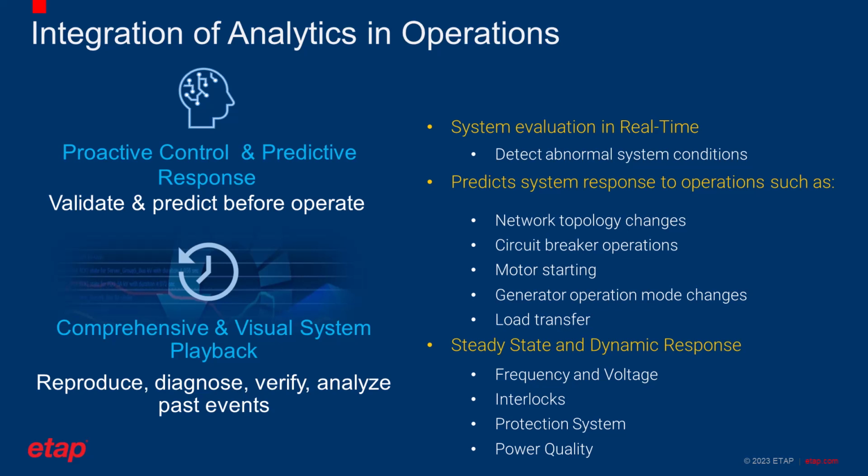The SCADA solution also provides the tools to predict electrical system response before an operation is executed, when the operator needs to perform network topology changes, circuit breaker operations, motor starts, generator operations, and more, including load transfers. They can simulate and validate the response of the electrical network to avoid unforeseen conditions such as overvoltage, undervoltage, underfrequency, protection system operations, power quality issues such as resonant conditions. The predictive simulation allows you to see the steady state and dynamic response of the electrical network.